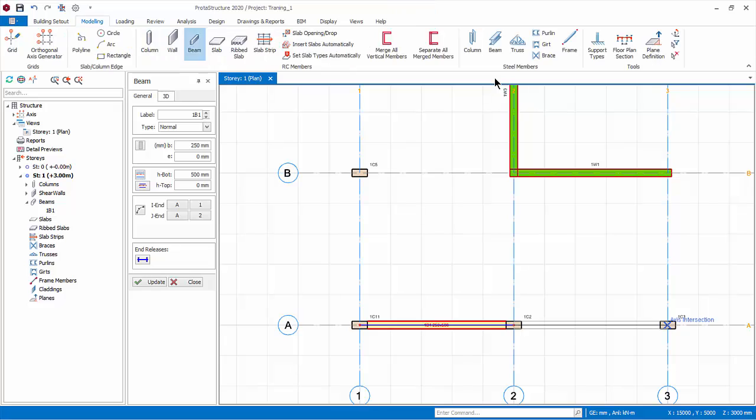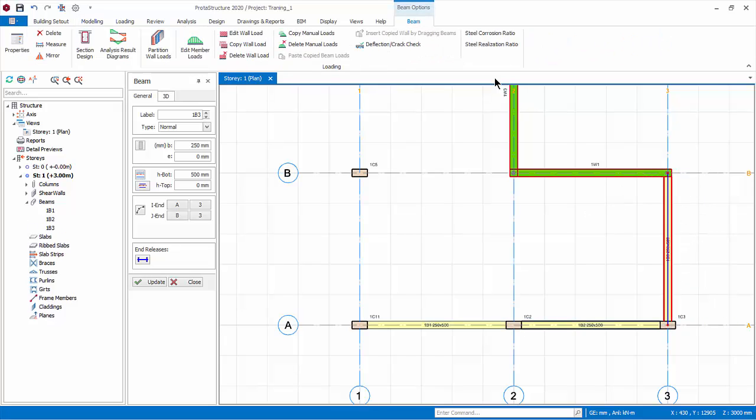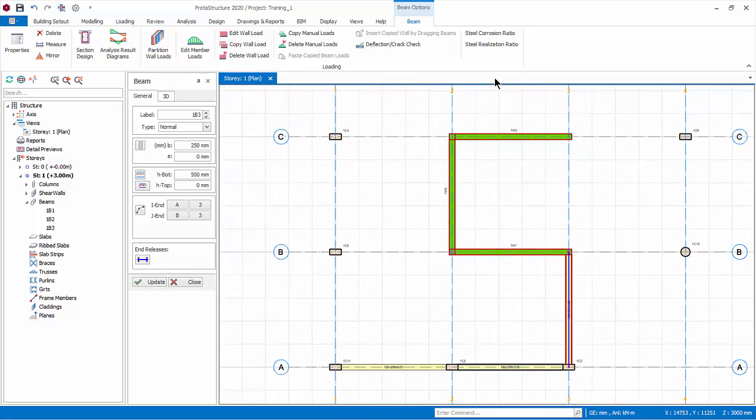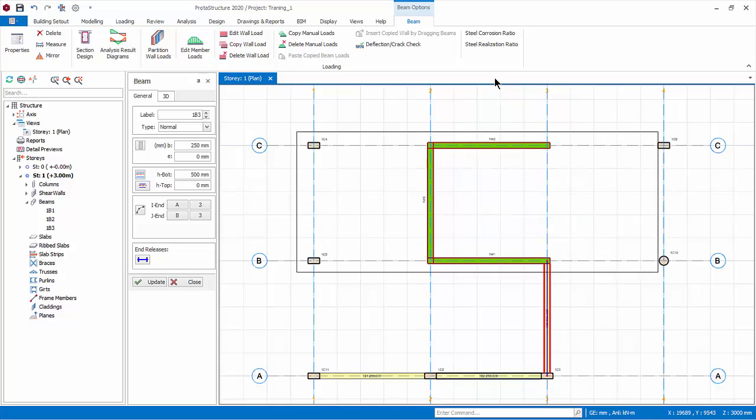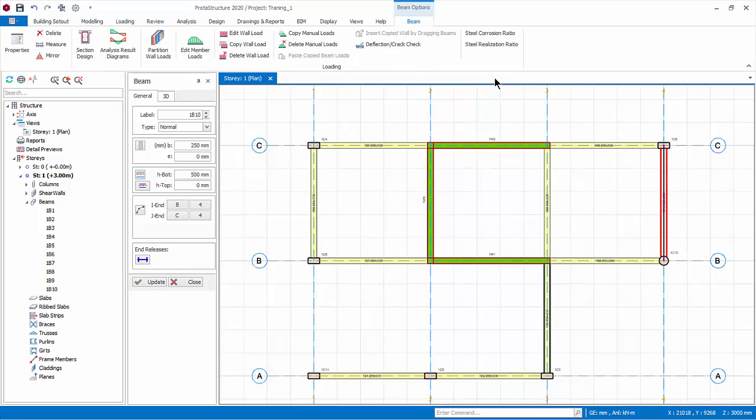Notice that you can continue to create beams from the previous beam continuously. Right-click to end the beam insertion, after inserting the three beams as shown. To insert a group of beams, you can draw a window enclosing the insertion points. Left-click on the upper left of the window, then left-click on the lower right of the window. Beams will automatically be inserted between columns and walls.